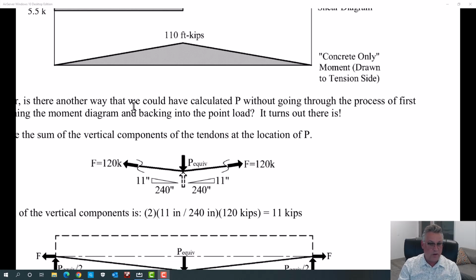And that's the way to think of pre-stressed concrete: we stress these tendons and all they want to do is go straight. They just want to be straight between the two ends being pulled. Something's resisting that. Well, that's the material resisting that. The concrete will be resisting that. But if you think about it in terms of loads, this equivalent load is what is being applied to that tendon to keep it in exactly where it is. Think about it floating in space.